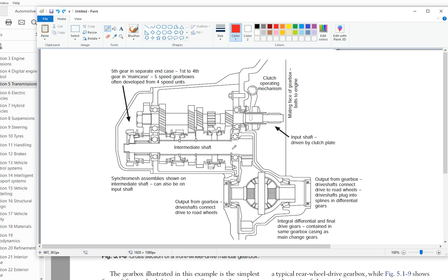The way it works is you have this synchromesh, and so there's this synchromesh sleeve, and the synchromesh sleeve has teeth to it. Okay, so it has three positions. Of course, there will be a neutral.